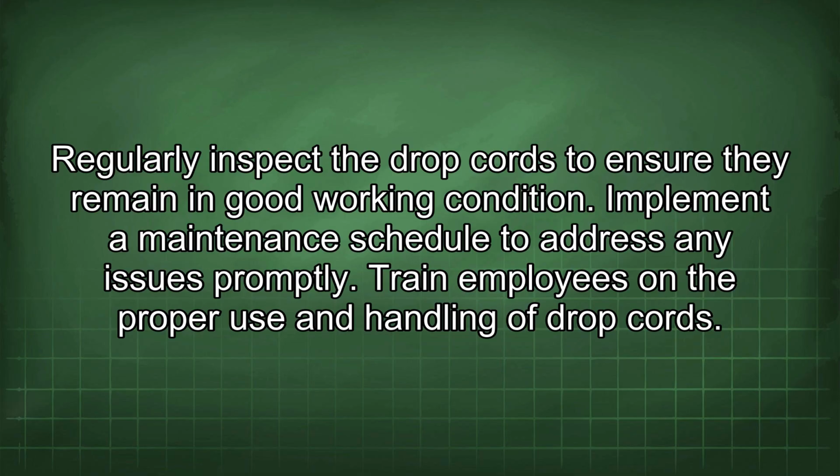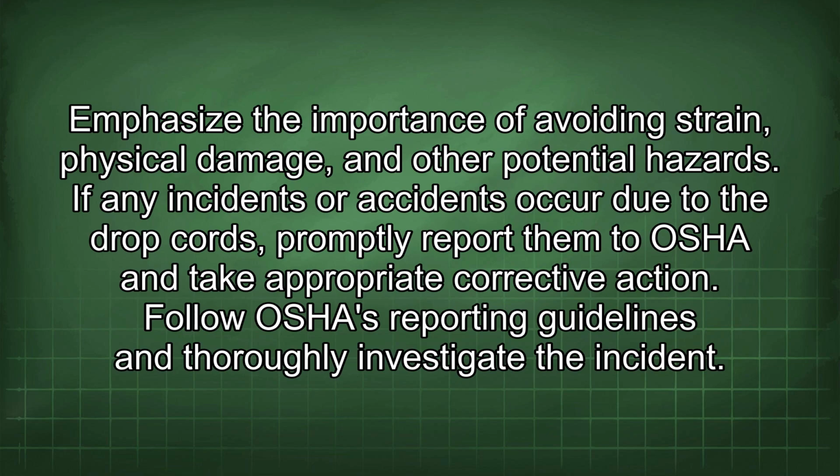Regularly inspect the drop cords to ensure they remain in good working condition. Implement a maintenance schedule to address any issues promptly. Train employees on the proper use and handling of drop cords. Emphasize the importance of avoiding strain, physical damage, and other potential hazards.